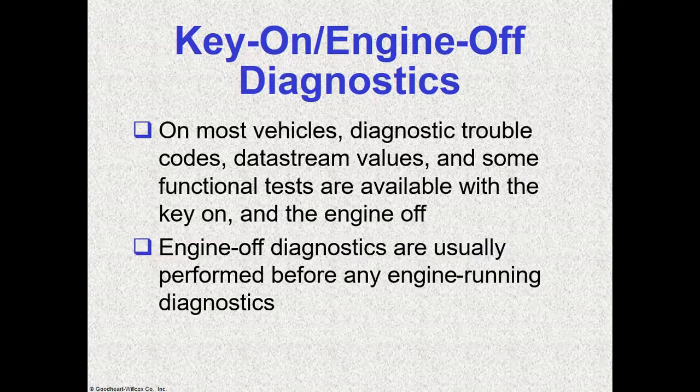Engine off diagnostics are usually performed before any engine running diagnostic. Sometimes the reason is, for instance, you want to scan the car but not heat up the engine, based on whatever test you are doing. That gives you the luxury of scanning the car without the engine running.